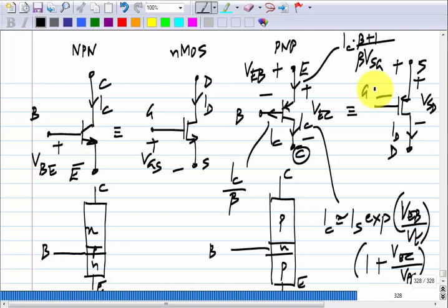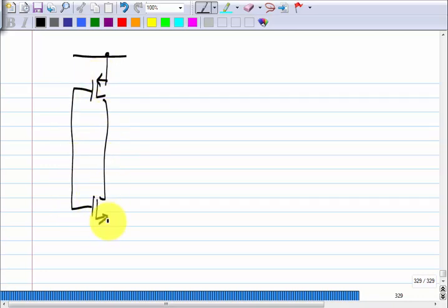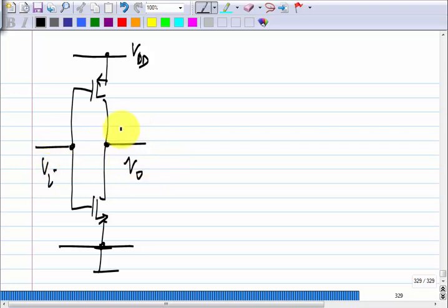So, the question he was asking, we can make a CMOS inverter like this. This is the basis for all the CMOS gates. If you want gates with more inputs, each of these PMOS will be replaced by parallel or series combination of PMOS, and NMOS will be replaced by parallel or series combination of NMOS.